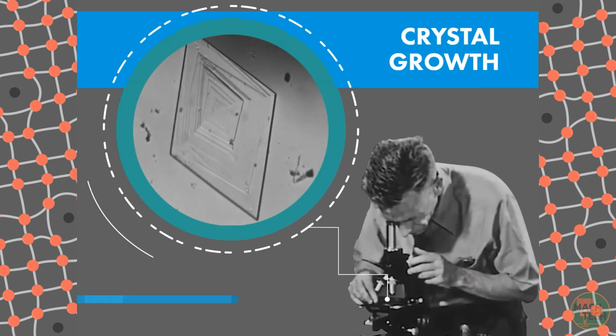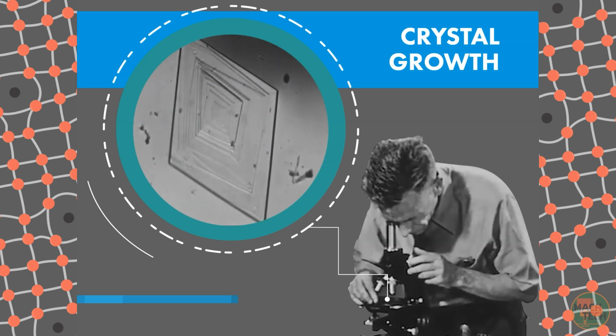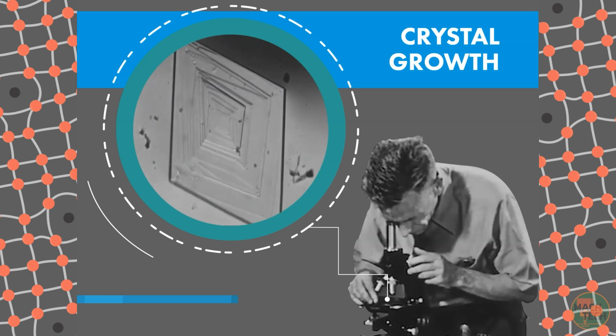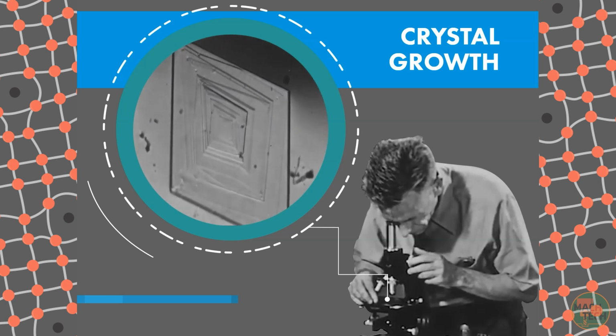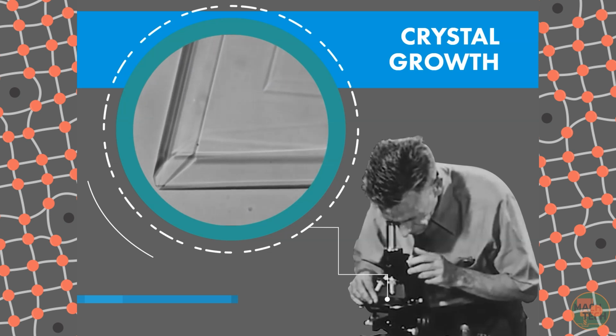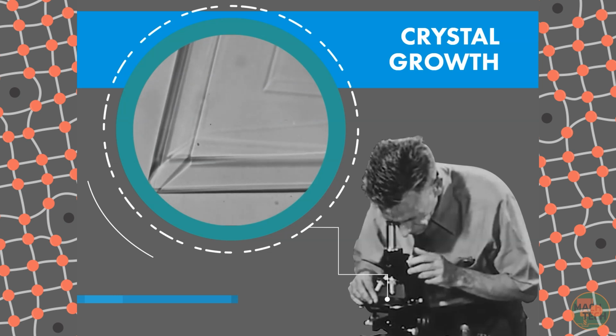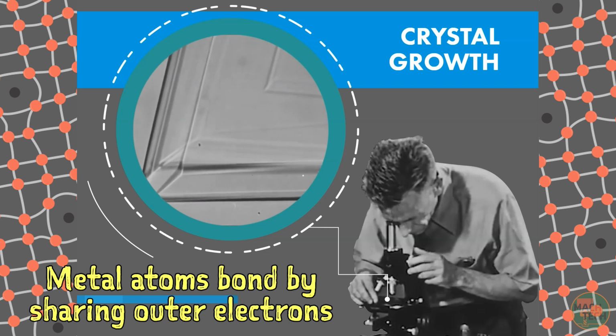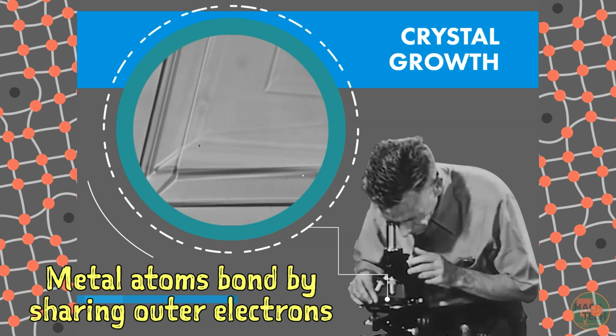As a liquid substance begins to turn into a solid, the atoms or molecules come together, attaching themselves to a nucleation site and gradually building upon it. They form a regular repeating pattern as more atoms or molecules join the structure, essentially sticking to each other like Velcro through chemical bonds. To be specific, metals bond when neighboring atoms share their outer electrons. It's actually not as strong of a bond as, say, a covalent bond, which is the kind of bond in ceramics. The comparative weakness of this bond is actually what makes metals ductile.